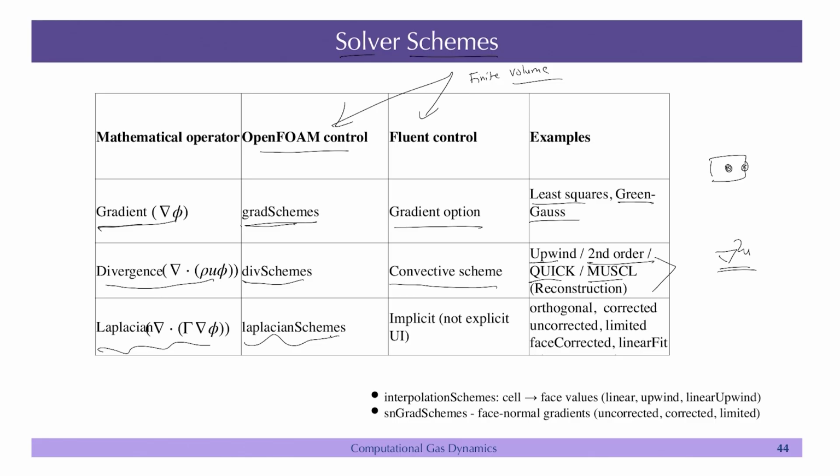You do not have to choose that, and the reason for that is, as we have discussed earlier, that the elliptic equations, or equations of this nature, like the diffusion equation, are stable with central differencing schemes, whereas for the convective equation, if you have del u by del t plus c del u by del x equal to mu del square u by del x square, this part you can use central differencing, but here you have to be very careful because this represents a hyperbolic system. So, in Fluent this part will be inbuilt, and for this you have to choose the scheme, you have a choice.